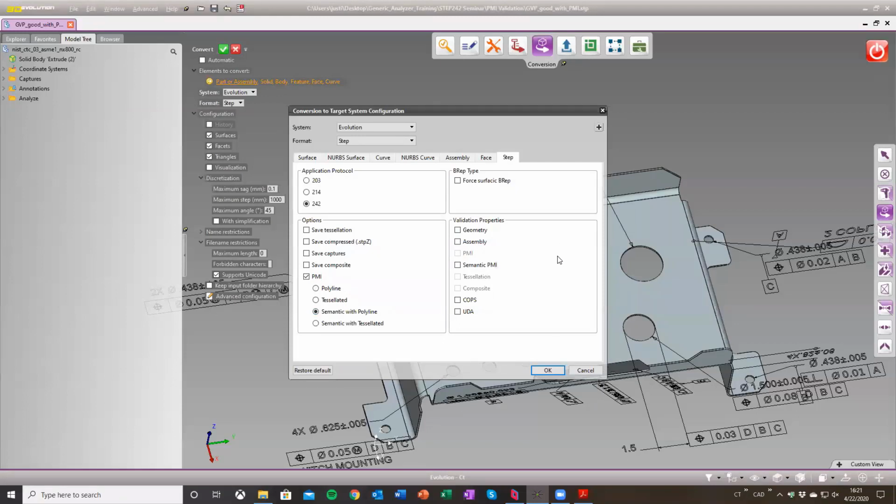Yes. You know the use case, the Airbus use case you presented tonight, is specifically something like that. The STEP file was produced by CATIA, and then we validate the CATIA STEP file. In fact, it's not a STEP file we produce with our own software. So yes, the answer is definitively yes. You can validate STEP AP242 written out from any CAD software as soon as it's compatible, properly supports the standard, and has the validation properties inside. Yeah, that's a great question.